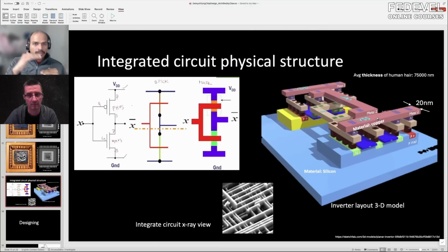At the higher layers, it's all the metal wiring connections. But this can create capacitors and resistors or something like this. The active capacitors are still on the lower layers. But we can use the higher layers for capacitance or inductance just purely based on their geometry, right? If you put two wide sheets next to each other, that is a capacitor by nature of its properties. Similarly, if you have a conductor and go around in circles, that forms an inductor. Yeah, this is interesting.